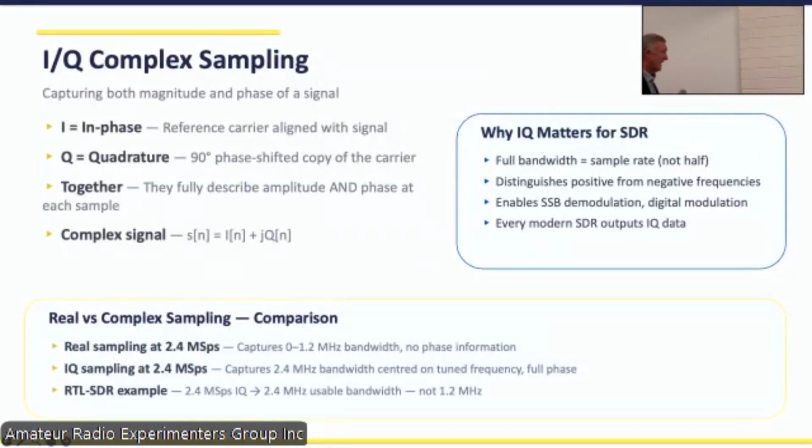So IQ is made up of two components. There's a phase component and there's a quadrature component. The important part to know, though, with IQ is there's a significant advantage to it when we're coming to the A to D sampling side. When we have the output as real, it must be sampled at twice the frequency. When we sample in IQ, you only have to sample at the frequency, plus a bit. But it's literally a minor bit.